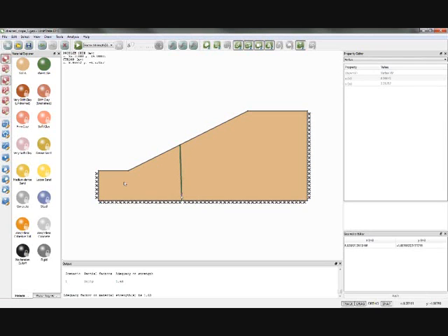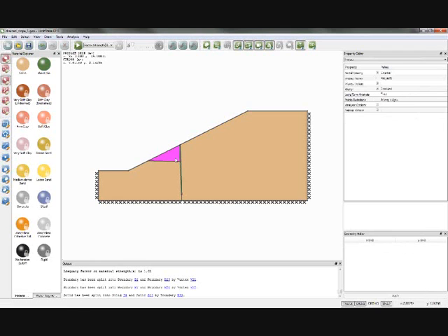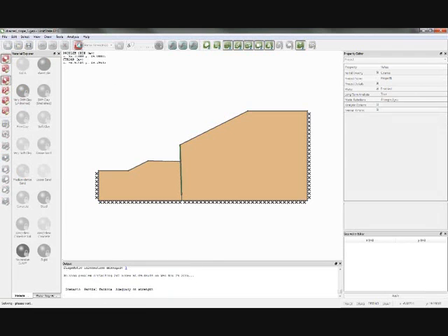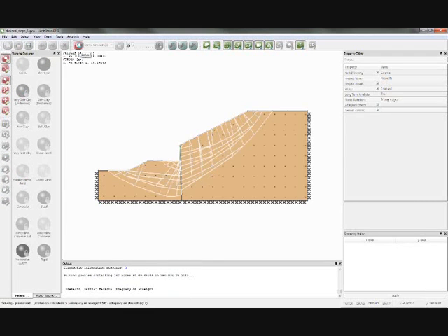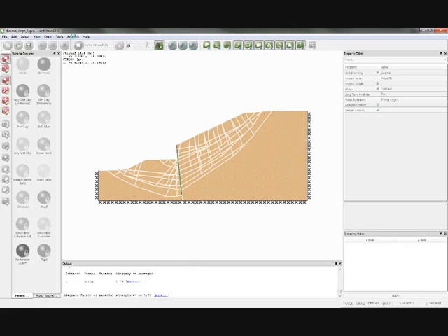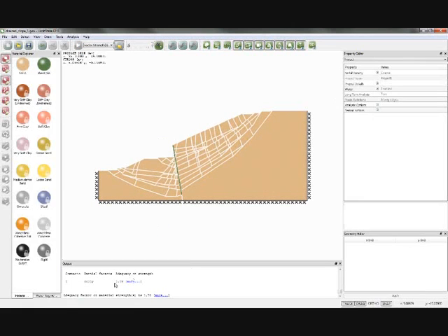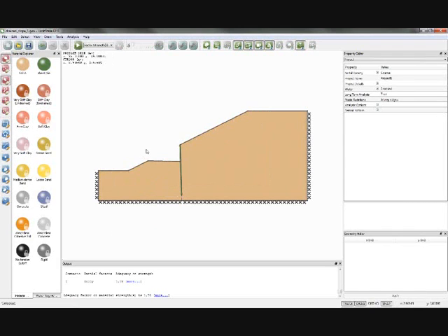And if you have the long wall, then if you want, that might facilitate, if I draw a line there, excavation of material if you need somewhere to do some construction, and you can look at how that stability plays out in that particular case. So here that wall has given us stability of 1.78, so that's still higher than the original 1.63. So hopefully you can see it's quite easy to play around with the geometry and explore possibilities.